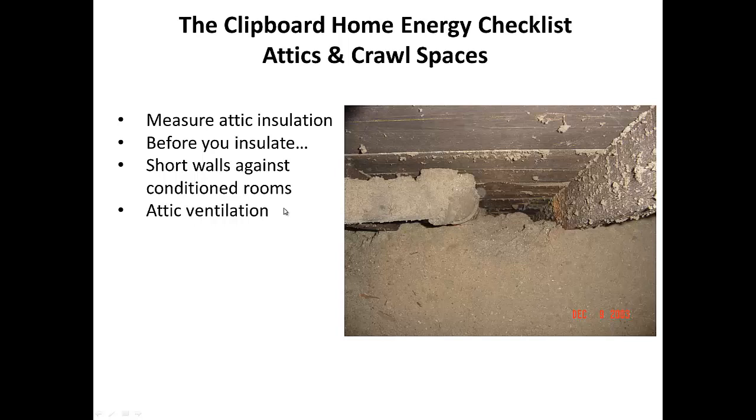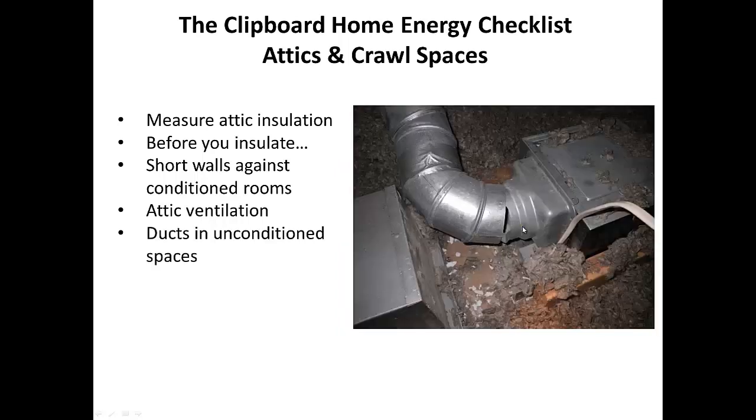Now, another thing to be watching for when you're in the attic is attic ventilation. You have soffit vents, which are down low in the attic, that you can see when you're on the ground looking up from the outside. And then you have upper vents, so that in the summertime all the hot air that's in the attic has a way to move out. But what we see here is that over time, or maybe with a bad installer, the insulation is covering up the soffit vent that's at the bottom of this insulation here.